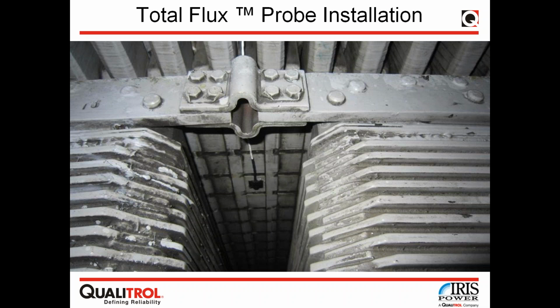Because of that, Iris does not produce a probe that can be installed that way. However, some other people experimented with a similar approach. If you make a coil and push it through the air vent from outside of the core diameter, it is possible. So the answer is yes, possible, but not highly recommended, because you might not be very precise in positioning the probe, and it could hit the rotor.